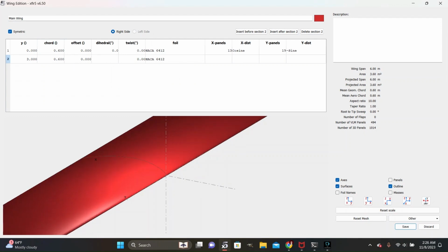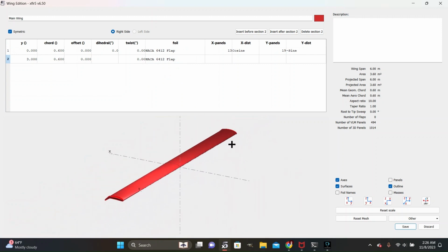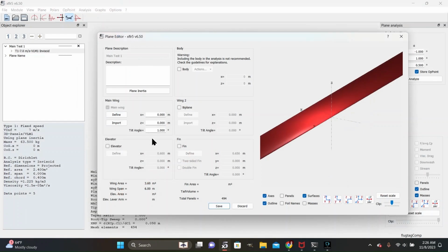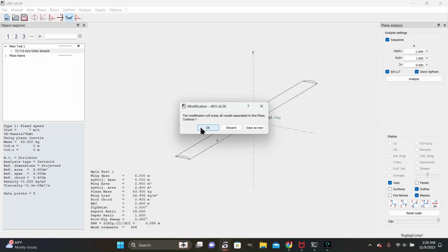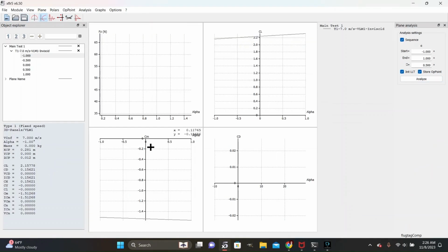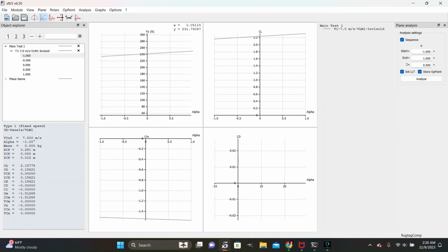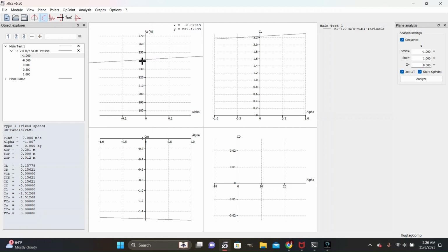This is going to differ slightly from our predicted Reynolds number, but it's still within a similar range of magnitude, so it should be accurate enough. And so here we are now generating around 240 newtons of lift, which is pretty close to what we're looking for.